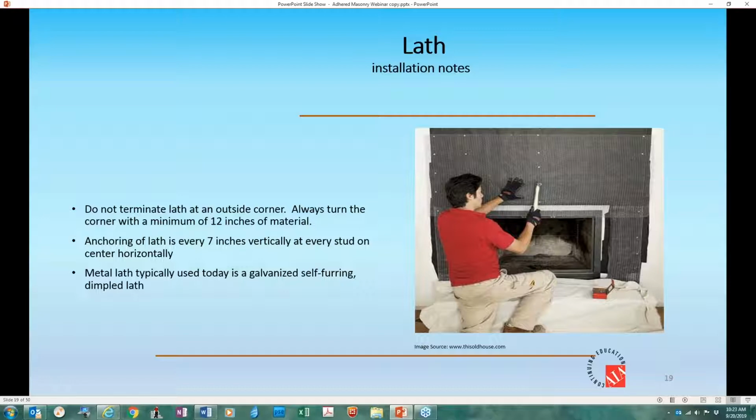Cutting is really easy. For those in the trade, always use the red tin snips. They cut to the right. That's going to give your hand a lot better chance of not coming out as a bloody mess. And the cutting shears that you can put on your drills have actually become the primary way to cut it. They're very efficient. You can do it with a battery operated drill, and it's going to give you a good job.